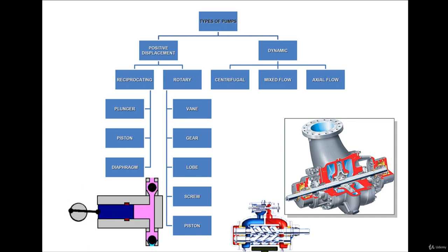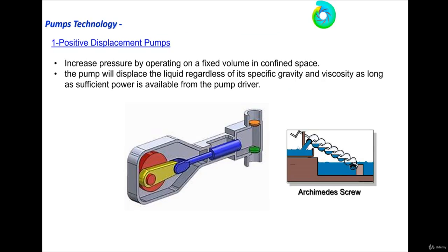As we know, the momentum of the fluid is mass times velocity, and the velocity is a vector with magnitude and direction. If you change both magnitude and direction, this is the centrifugal type. If you change only the magnitude, not the direction, this is the axial type. And of course each one has different characteristics, a different range of flow and produced head.